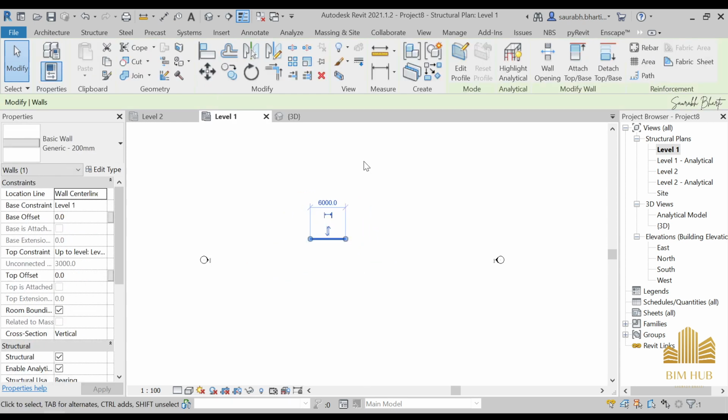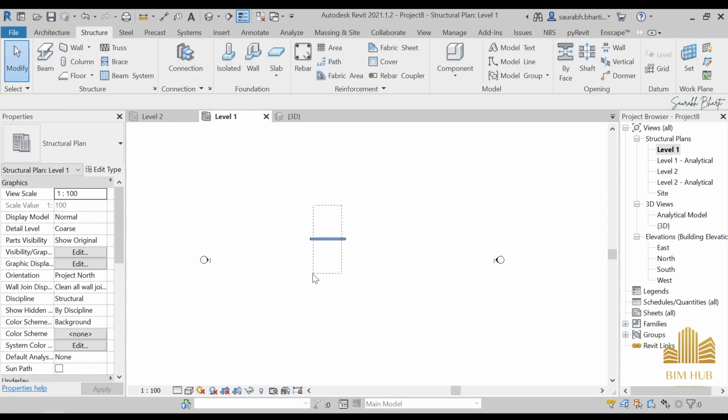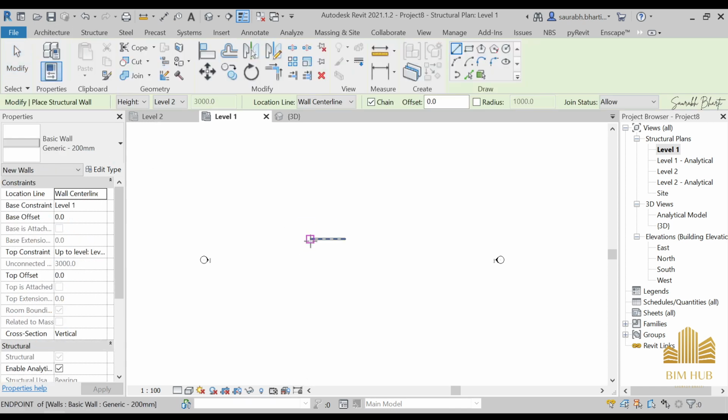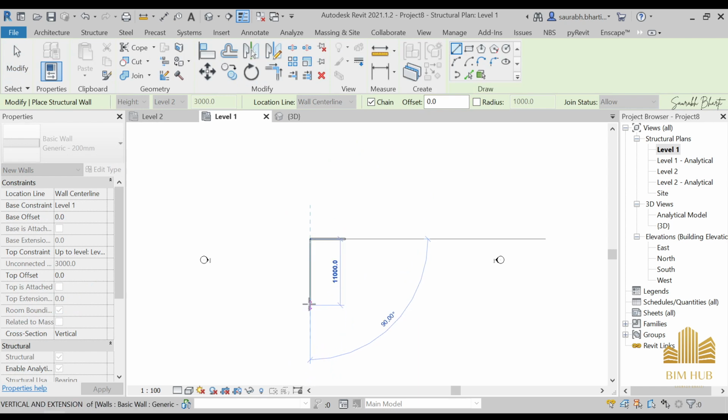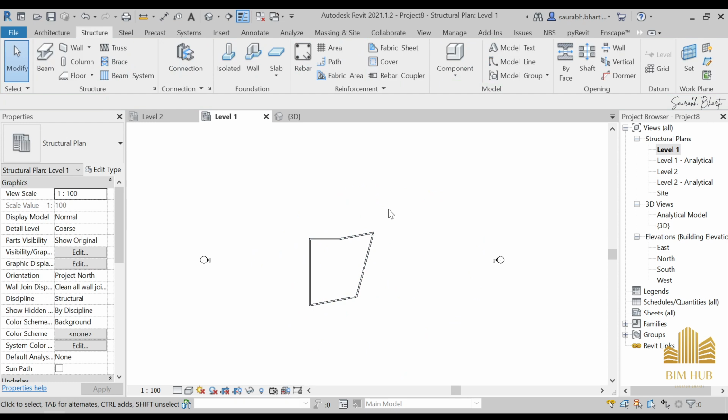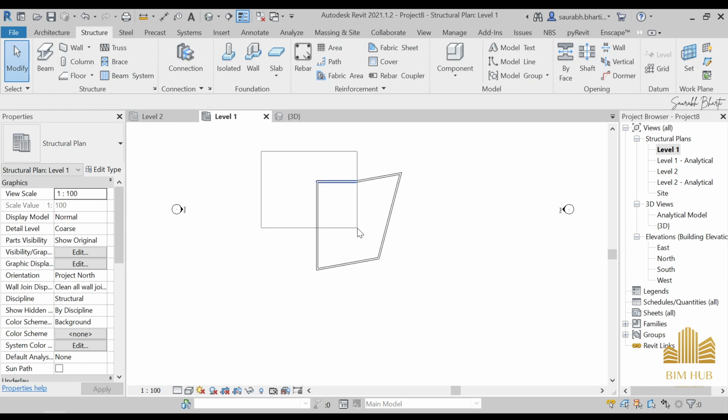And then what if we want to do some modification? So let's just delete it. Here I've not told you two more things. I'm selecting this line. You can use this line to draw at any angle like this. If you are selecting from left to right, I click my left mouse button and drag my mouse over here, and whatever it is touching is being selected. If you do the same thing from the right side, as you can see, this is touching it but it is not being selected.